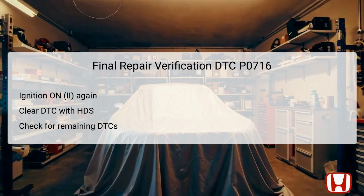After clearing the DTC, it is essential to start the engine and perform a series of checks. This includes disabling the Vehicle Stability Assist (VSA) feature through its off button and letting the vehicle run in drive at speeds exceeding 12 miles per hour for over 10 seconds. Finally, check for any remaining pending or confirmed DTCs with the HDS. A verification that no DTC P0716 is indicated confirms the effectiveness of the repairs conducted.